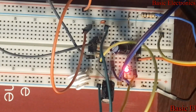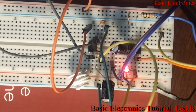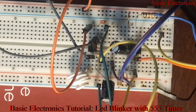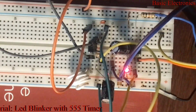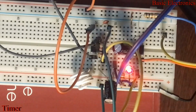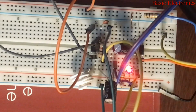As you can see, the audio cuts off when the LED is off, and turns on when the LED is on. So we're controlling pin 4 of the audio frequency astable multivibrator directly from pin 3 of the low frequency astable multivibrator.